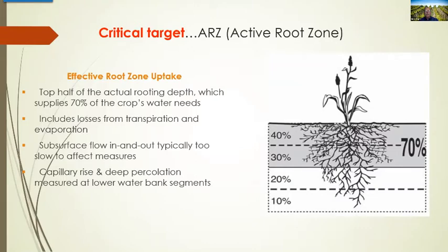That's exactly what happens in a sandy soil in a block. So if you're dripping in that spot and the next dripper's 36 inches away or wherever it's located, you may not be getting a good wetting front or a good wetting pattern. So it's really important to understand the dynamics of your soil.